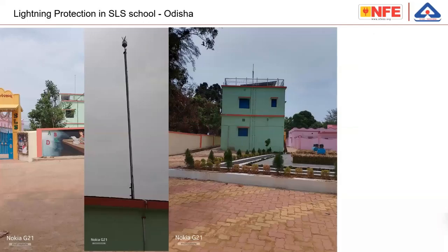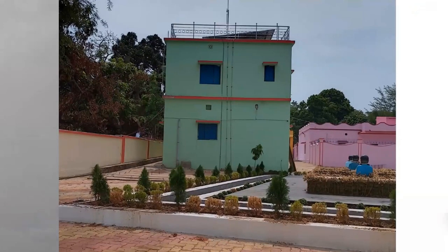I'm just zooming the picture. These are the electrical lines, one from top to bottom, the third is a conduit through which the electrical wire is running, and the horizontal one is also electrical wiring. In practice, what will happen is if there is a lightning strike in this building, the down conductor is carrying an enormous amount of current, and the vertical pipe which is going from top to bottom of the building, there are two down conductors and one electrical wiring. This electrical wire and the wiring and the connected equipment will disappear immediately. Disappear in the sense it is completely going to burn.